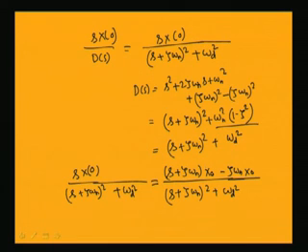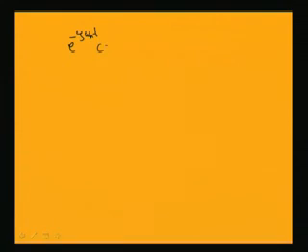So, the first part, the inverse Laplace, will contain e to the power minus zeta omega n t into the cos term, and the second part will contain the sin term. So, this can be written as e to the power minus zeta omega n t cos omega d t minus zeta omega n by omega d sin omega d t into e to the power minus zeta omega n t into x0.